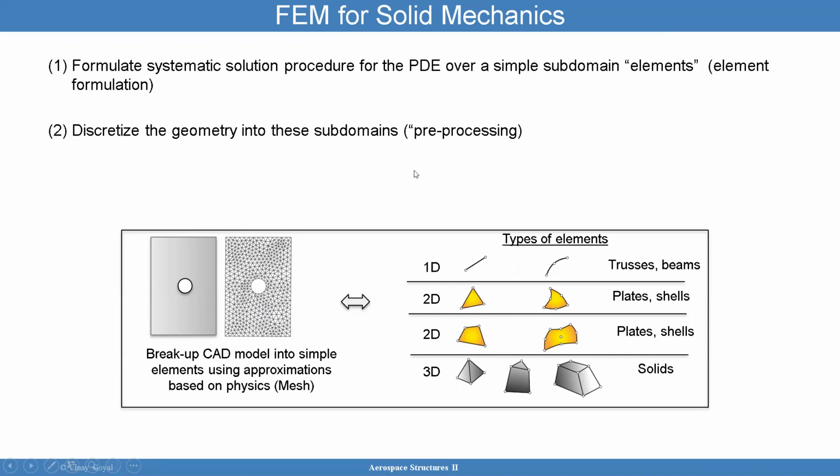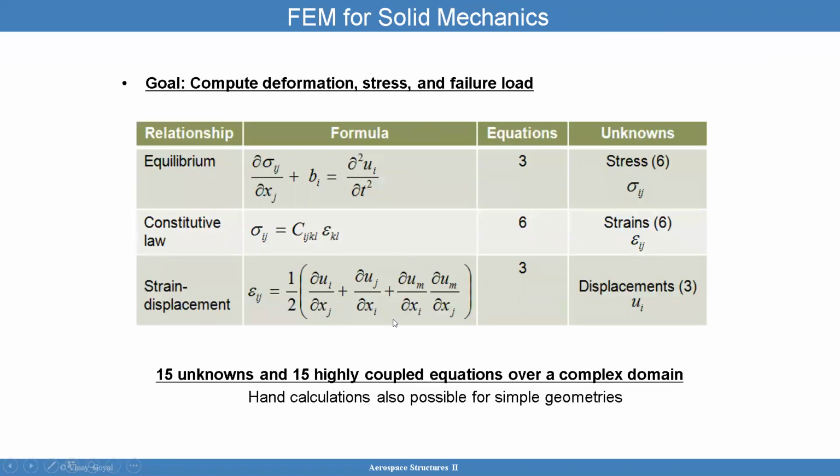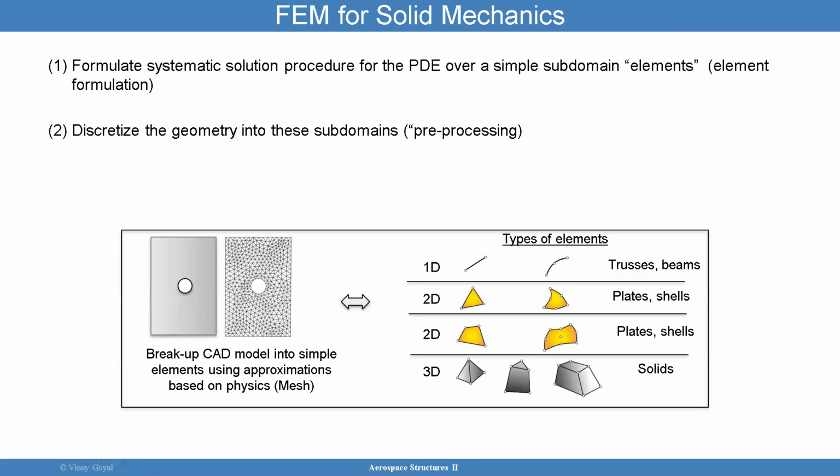And that square is what I will be using to solve these 15 equations, 15 unknowns. And so that's the good news: with finite elements, I can divide the domain into small pieces. And those small pieces can be turned into a standard element that applies to every single element in the domain. And using something called mapping, we're going to map a triangle to a standard triangle. And by mapping the geometry to a standard domain, I've simplified the problem, and I'm now able to solve these differential equations by connecting them back together.